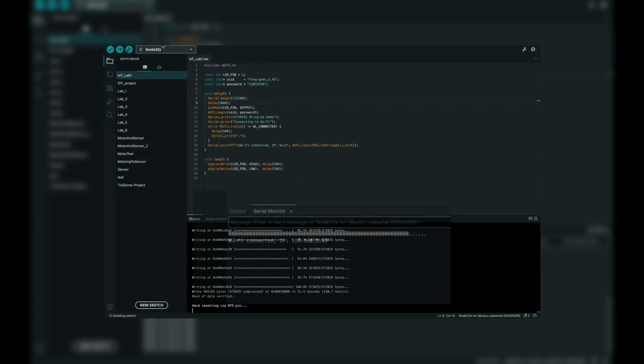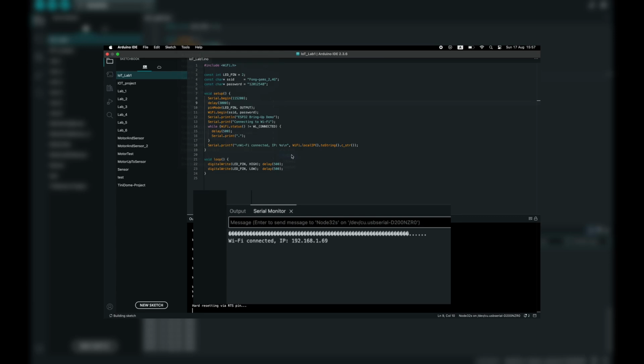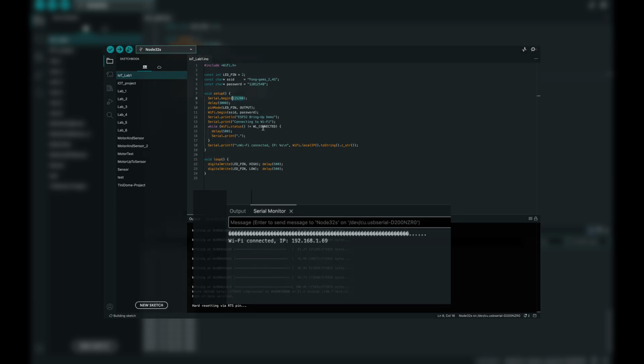And if you notice, you can see some missing characters appearing on my monitor. It occurs because I didn't configure my serial monitor to use the same baud rate as I set in the code, so I had to change it. And for the final part, the task is to get time from NTP.